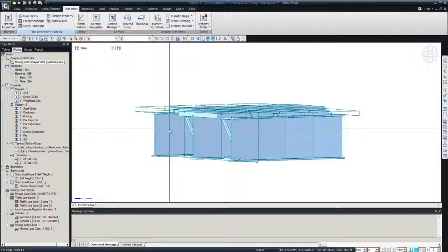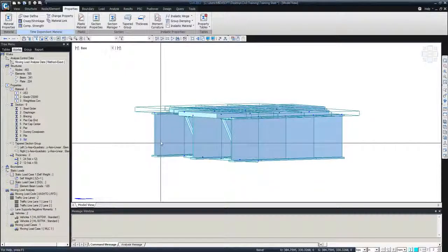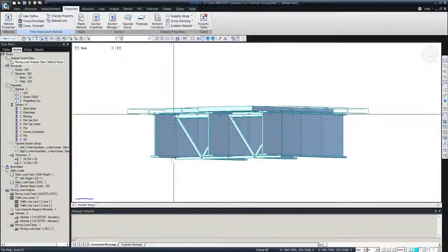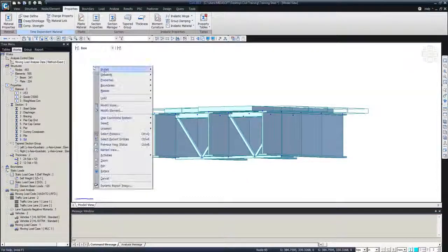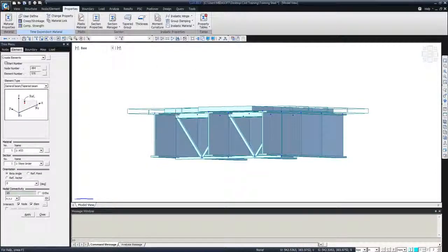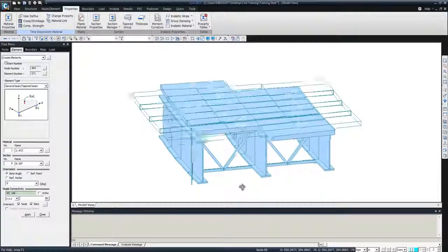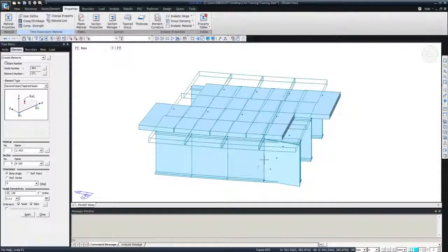But here's the thing, because we are using a beam element, the stiffener may not work exactly as you want it. But simply I can model it right now. For example, going to the element, create element from here. Let me select this as stiffeners, and then select it from here to there. Okay, the direction went wrong, but it's going to be something like an element right here, stiffener.